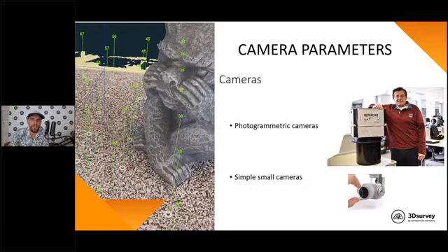For these cameras, the traditional workflow was to calibrate them. That meant calculating all the camera parameters, which are focal distance, distortion parameters, principal point location, and these sorts of things. You would do the calibration once, and then keep using those parameters for a few months. These parameters would stay fixed, and after a few months, you would repeat the calibration. This was possible because these cameras were called metric cameras. They were made from special materials that don't contract much.